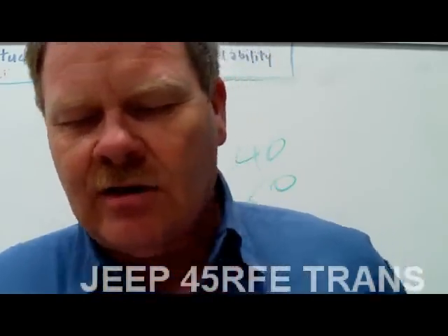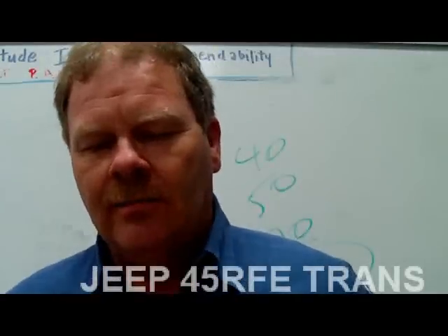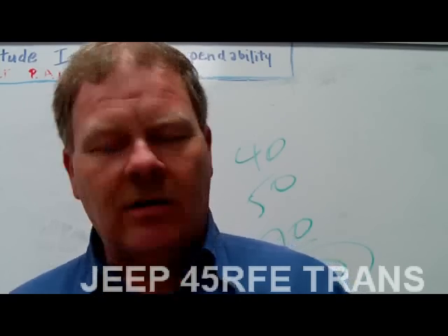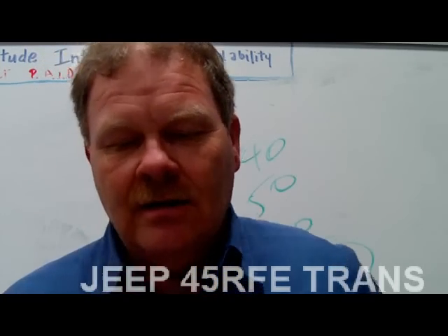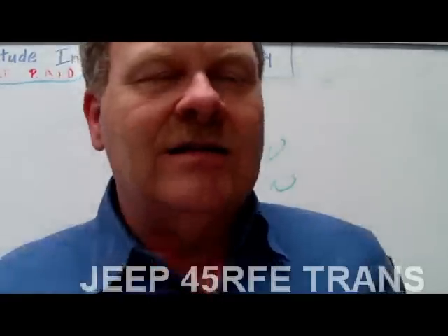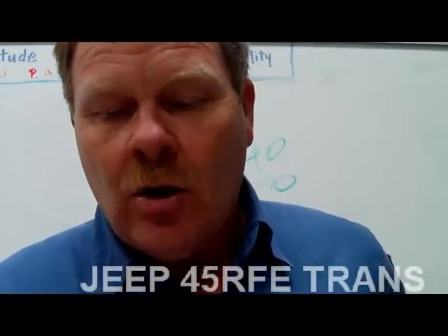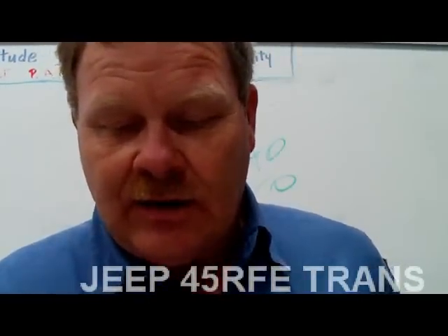The transmission computer receives power input from two sources, fused battery power and fused ignition switch input. It's got power all the time, and it knows when you turn on a key. It's not just sensing when you turn on the key, it's using that power for stuff. And it also has a ground, which you have to have to complete any power circuit.